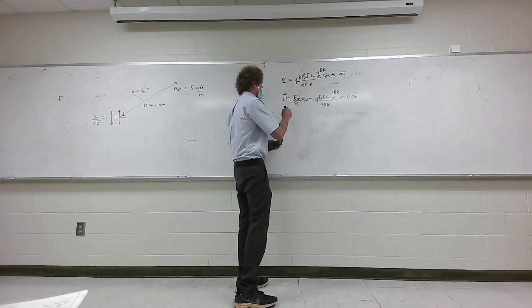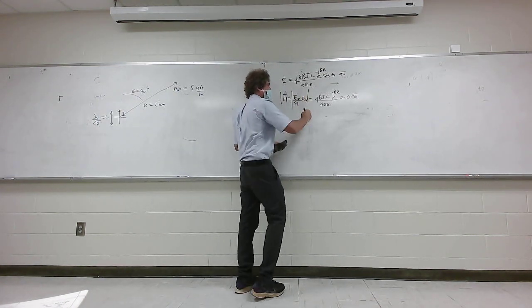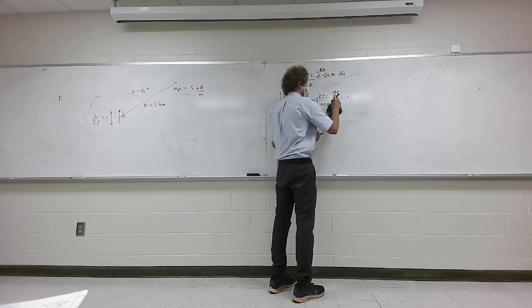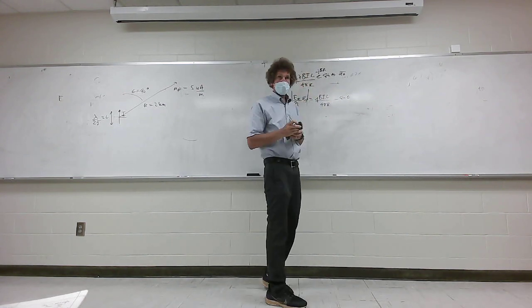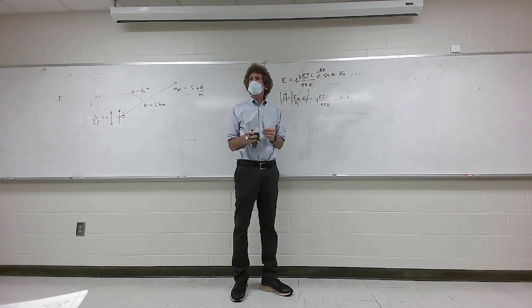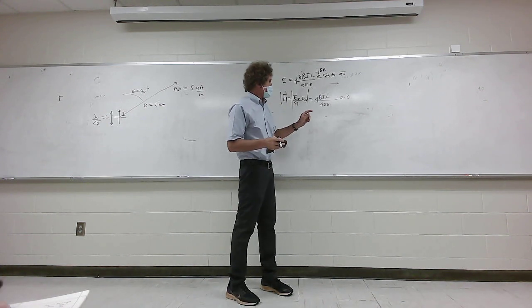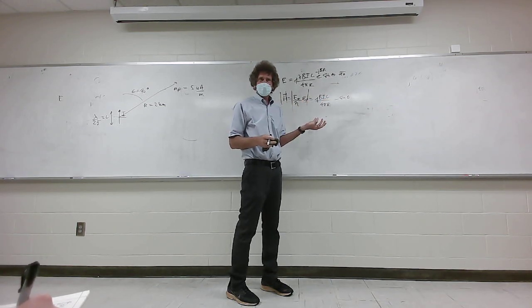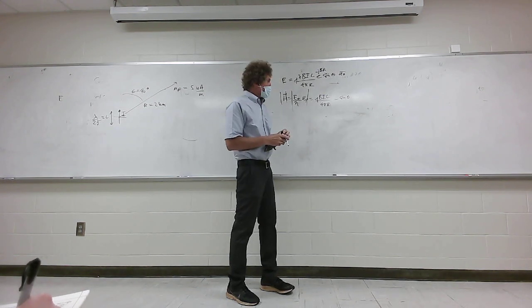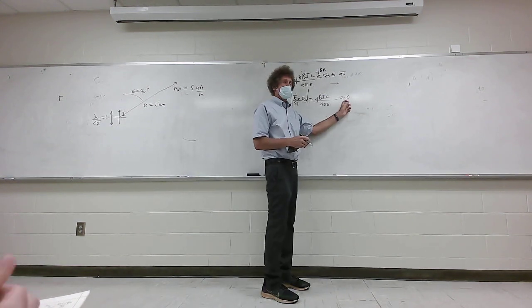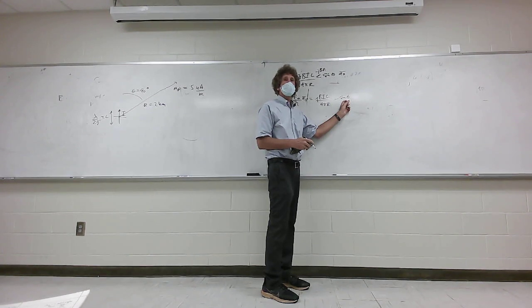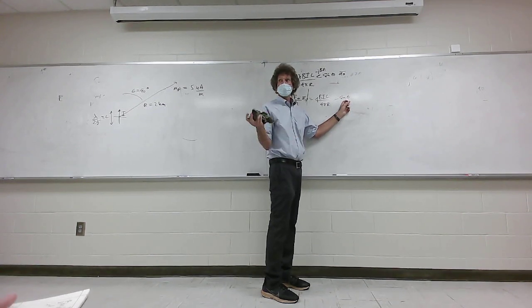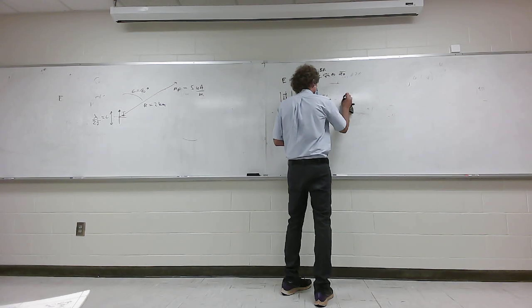I'm looking for a magnitude of the H field, right? Magnitude gets rid of this and gets rid of this, doesn't it? You agree, class? We forget about the direction of that. The next is, I got rid of e to the minus j beta r because that's a phase. It's like an angle of 30 degrees, correct? Now what do I do? Well, the angle is 90, right? What's the sine of 90 degrees? 1, so I get rid of that.